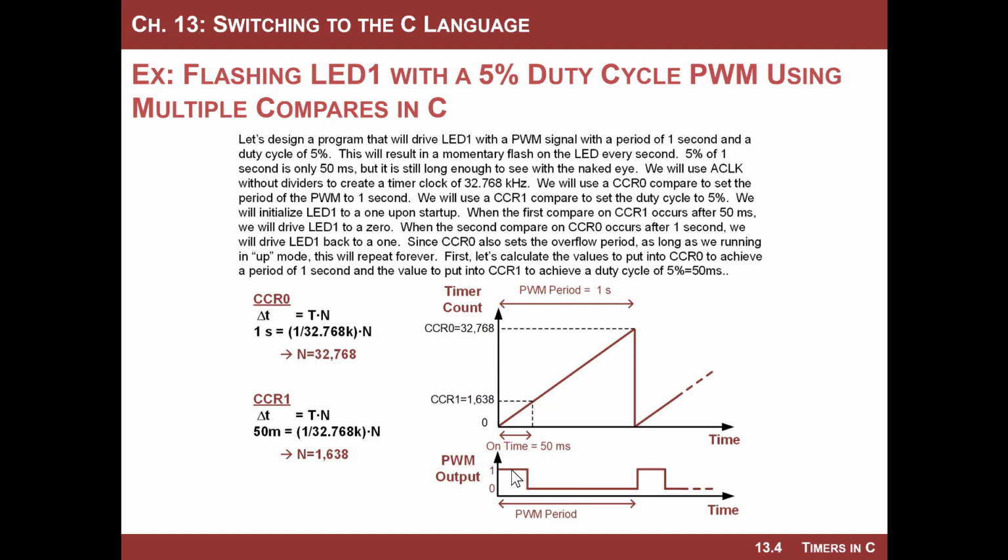They're very useful signals because that's how a lot of motors are controlled. Servo motors, continuous motion servo motors, DC motors: you can use these as control signals, but you can also use them to pulse things. For example, with an LED, if you didn't want to drive it full on all the time, you could turn it on for a little bit, then turn it off. You could get it a little dimmer than if you drove it all the time. They're used everywhere in electrical engineering and computer engineering, and they're awesome.